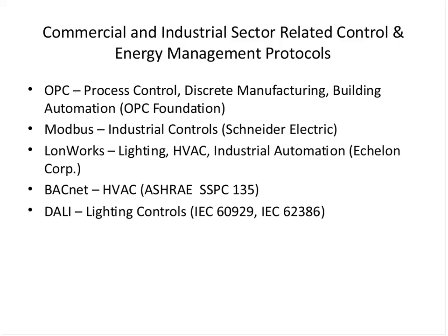And then DALI, which is also part of BACnet, which does lighting control. So these are some of the popular ones, there are many more, by the way, but I would say that these have big market shares in the commercial and industrial sector. Some of these are application layer. Some of them are application and have some specs for networking. But many of these can run just on a serial interface, like an RS-232 or 485.